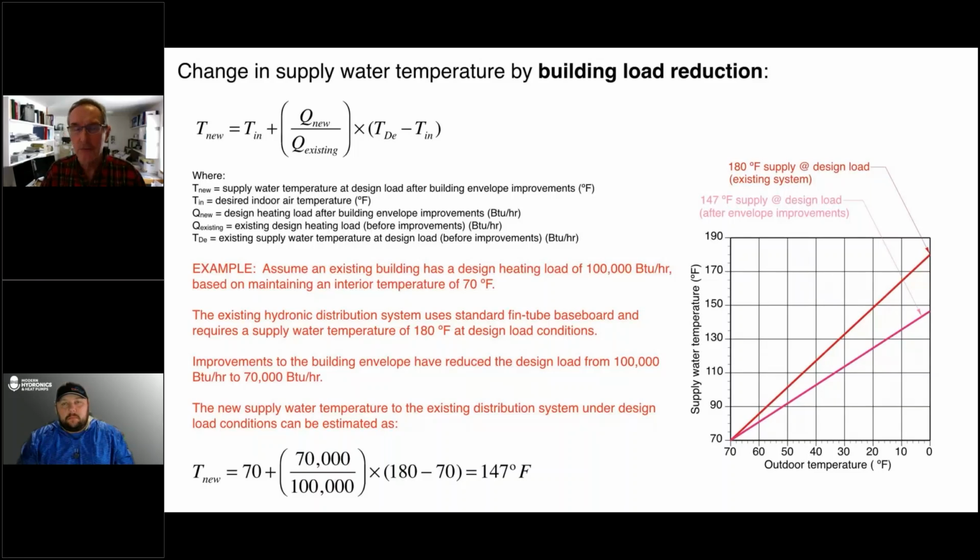These little fans run on about 1.5 watts each, like the fan in your desktop computer. They're enhancing convection at low water temperature. So yeah, you could run a fan and potentially squeeze a little more heat out of that radiator. How you would make that work aesthetically from a sound standpoint, I'll leave up to somebody else.